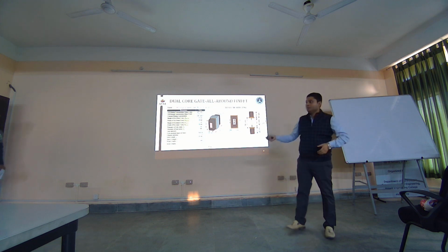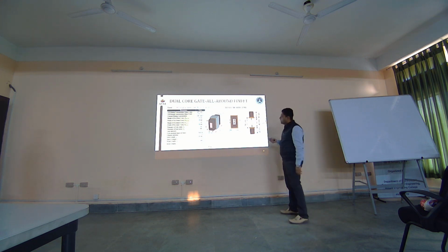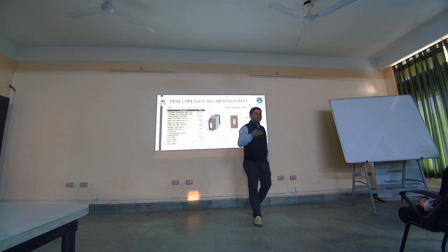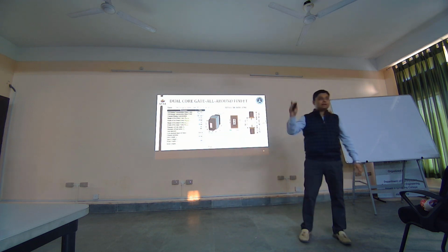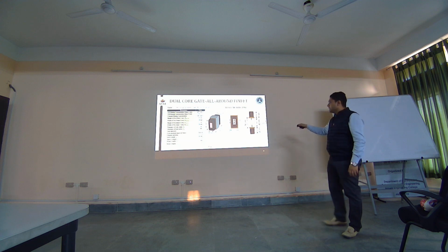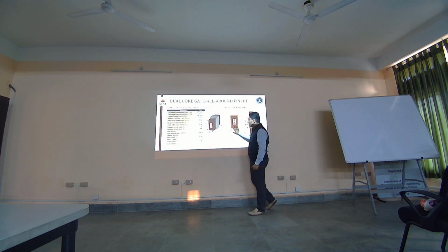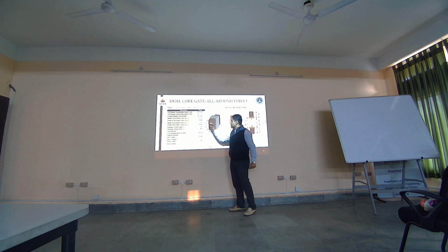In that case also, we tried to introduce a dual core source drain, so that the doping concentrations can be varied on the outer core and the inner core, just to check its performance. This was just a random structure that we did, but we had some interesting revelations. One of the most important things that we discovered is that since the body is entirely silicon, we do not need additional costs in the fabrication line. That is the first point.